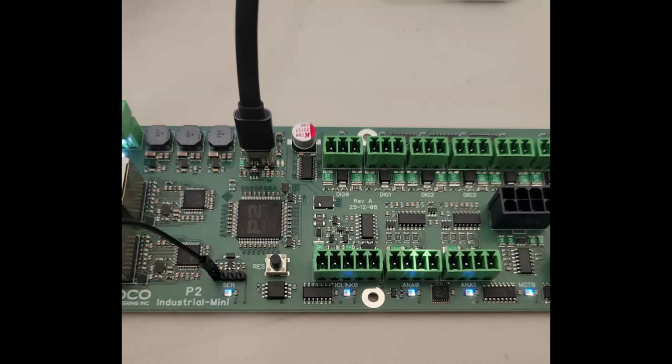I'm seeing three power supply circuits there. Is that meant to get the total power you need, or is it redundancy? Yeah, they're 5 volt, 3.3 volt, and 1.8 volt. Oh, they're all different voltages. Okay. Yeah, so some of the stuff like the motor signaling is at 5 volts. The LED signaling is at 5 volts. The P2 and the Ethernet chips and most of that expander logic is 3.3 volts. And then, of course, the core of the P2 is 1.8.